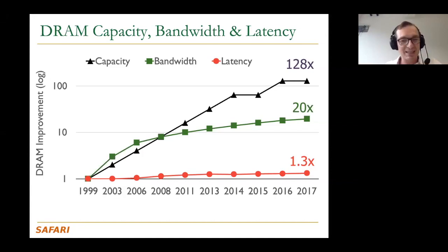So there are multiple issues here. One is the design mindset, which is very, very capacity oriented. And the second is fundamental issues. Fundamentally, capacity is traded off for latency and vice versa. We will see this very clearly in future lectures. If you've taken digital design and computer architecture from me, you've already seen some of this when we talked about memory. I said that bigger is always slower, and I mean that. The bigger memory capacity is always slower. If you want to make things faster, you want smaller capacity. No question about that.